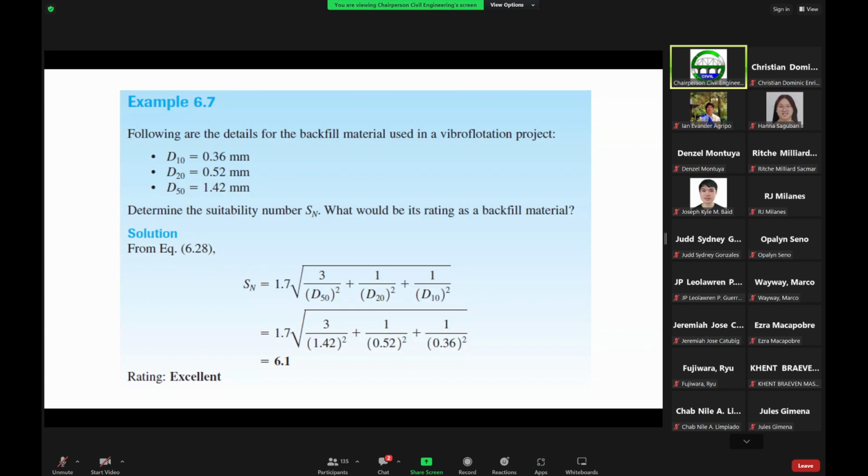So that means when we do ground improvement works in actual practice, these are quite sensitive to the material specifications. Otherwise, you cannot achieve the required ground improvement, or the required density that is being specified by the client, and that is always challenging in actual construction.